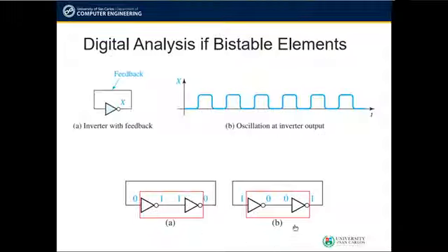The two circuits set up for the NOT gate here are now capable of holding an output value or state indefinitely. You can see that if we cascade two NOT gates in this manner and treat this end as output, which is 0 in this example, and use it as feedback input here, the output on this end will remain the same, which is still 0.